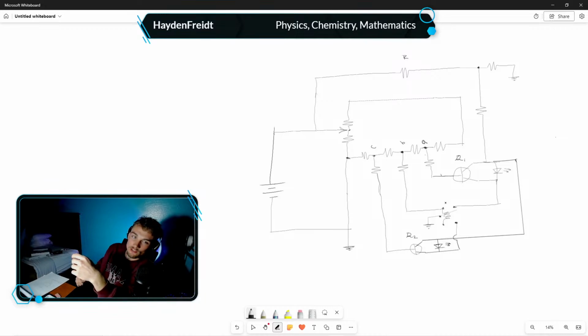I know what nomenclature in chemistry is, but in regards to other things, I don't know. Anyways, for the relay we're just gonna use L, which is the notation for inductors, and that's exactly what we pretty much have. We have this inductor here that's operating the lever of the switch. Bada boom, bada bing. And that actually requires 120 milliamps to operate.